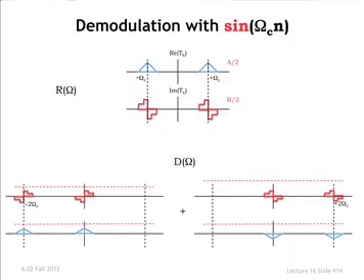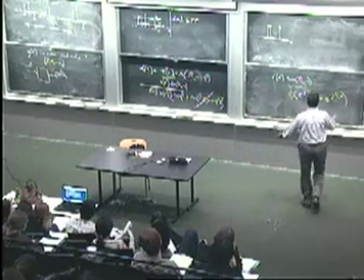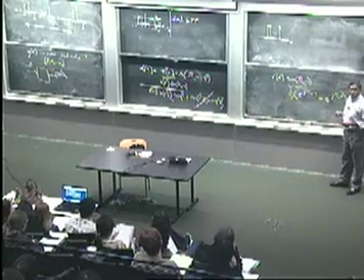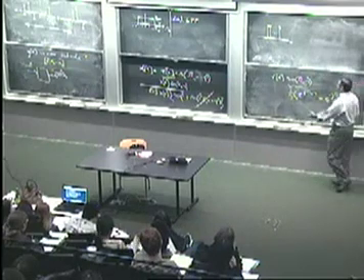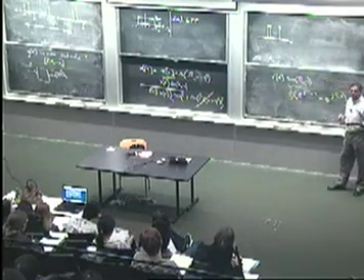If you think through what the shifting and scaling does, you see that it's a little more complicated a picture. The real part gets replicated around the 2 omega c region, but flipped over. The imaginary part gets carried over intact. And then for the replications around minus omega c, the imaginary part gets flipped over, and the real part gets carried over directly, except what was real before becomes imaginary now, and what was imaginary before becomes real now. You can track through all of that, and it just comes from applying standard DTFT results to the spectrum of the product of R of n and this.